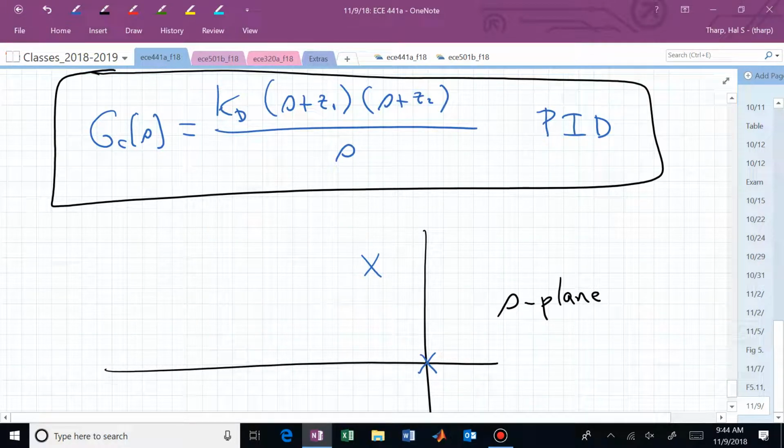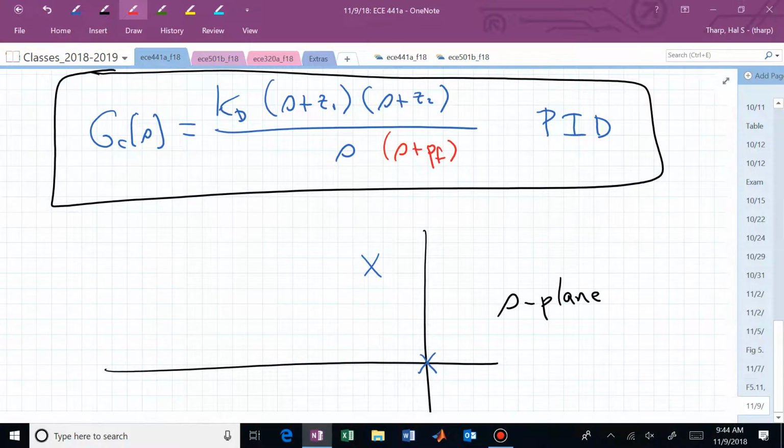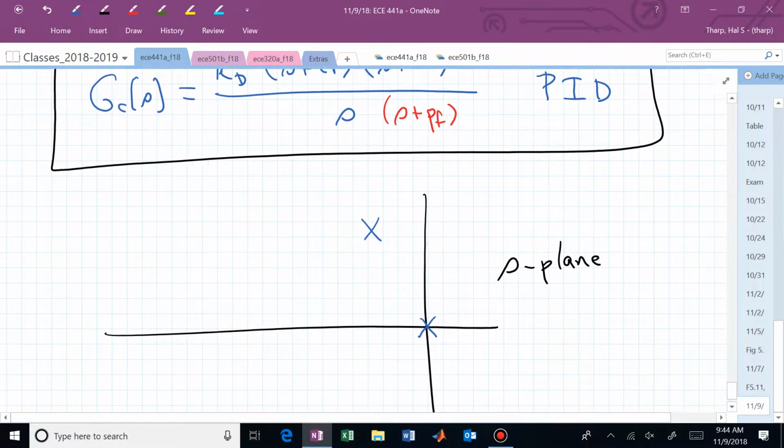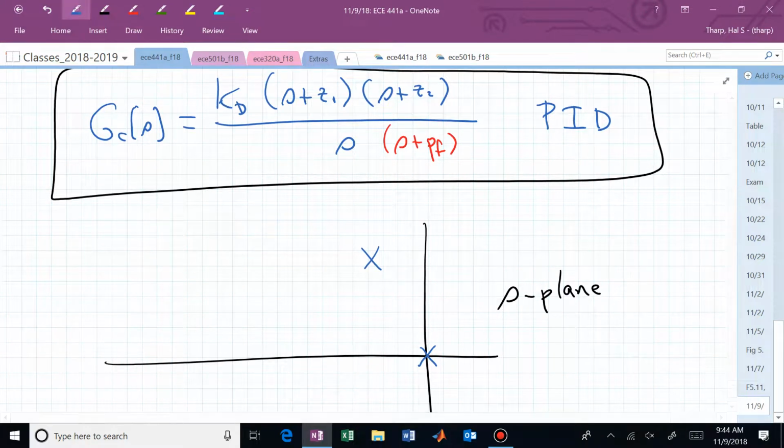Better steady state accuracy. But now we are actually, with this ideal scenario, I said we're neglecting this piece, didn't I? Neglecting that red factor, now we've changed our pole-zero excess. We have two zeros and a pole. Oh boy, that's going to help us. And this is the ideal design scenario. Now we get to place two zeros.